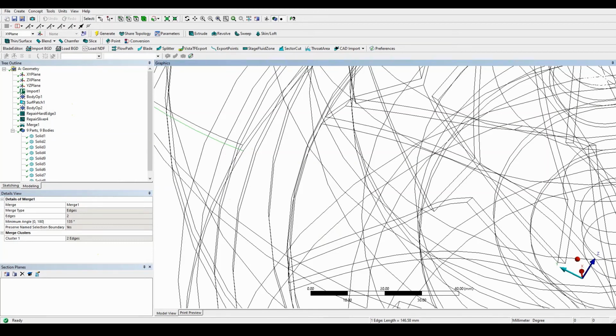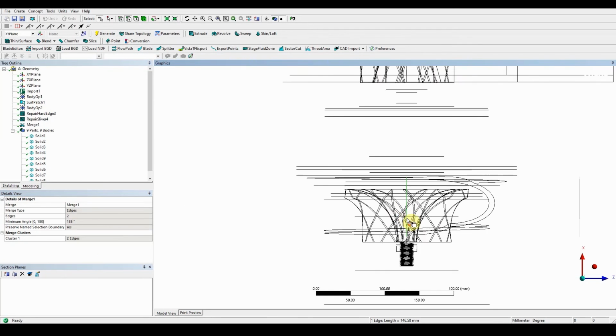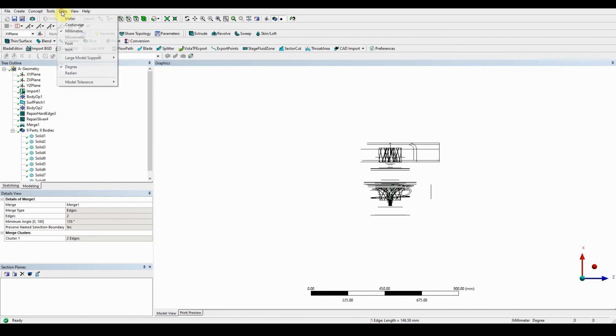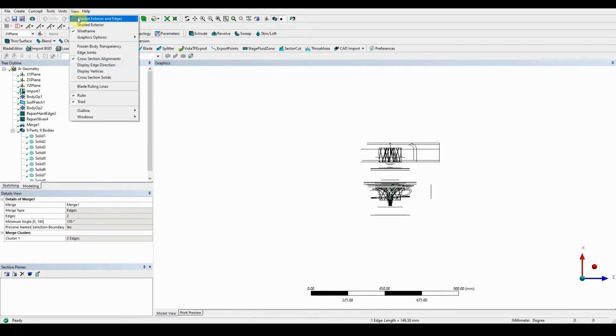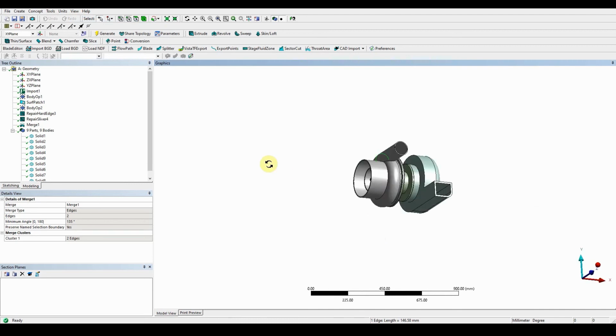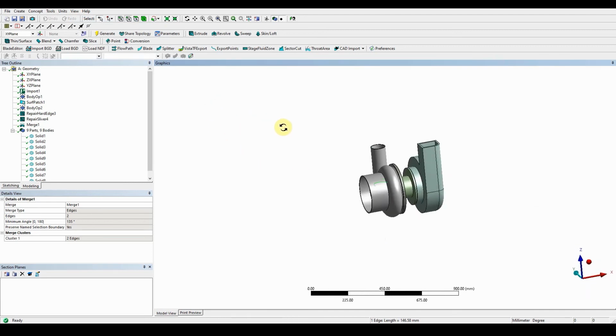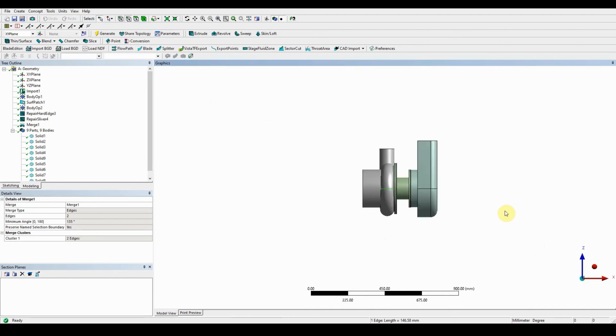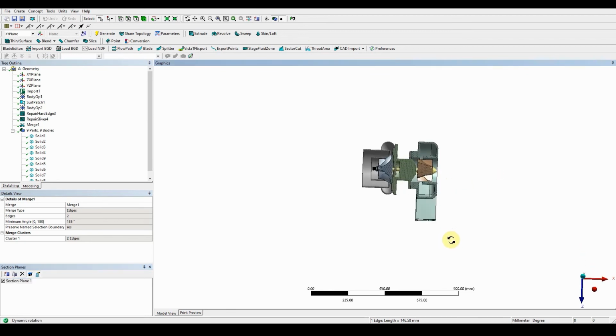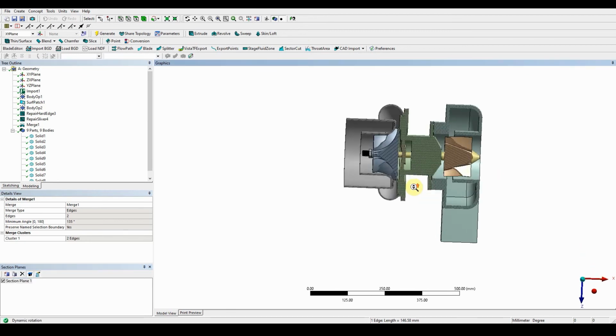So there are gaps and intersections between the two different solid parts of the external CAD, which we can find and see. So if we click on the line view, shade exterior, okay, so let's click on this, and then if I just cut this through here, we should be able to see where those problems lie.